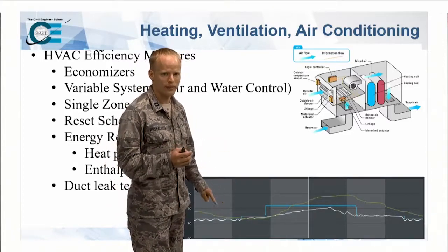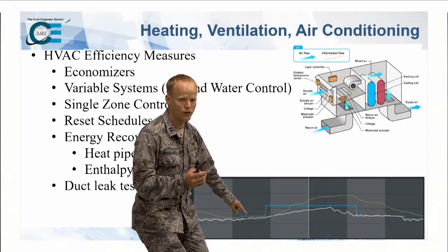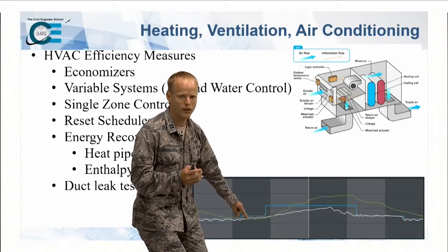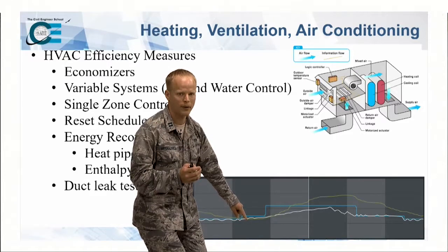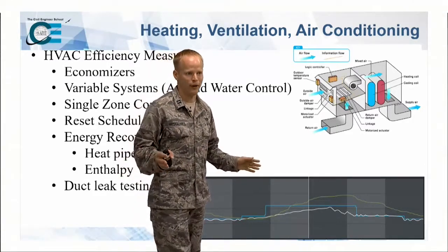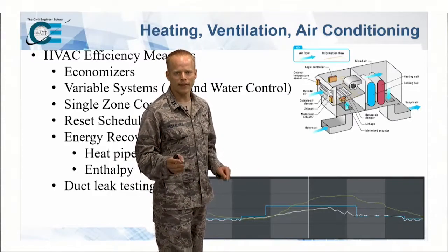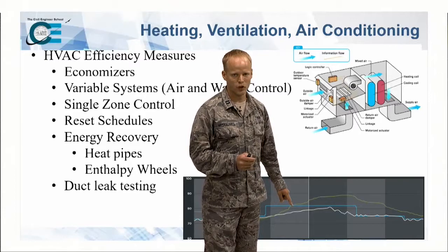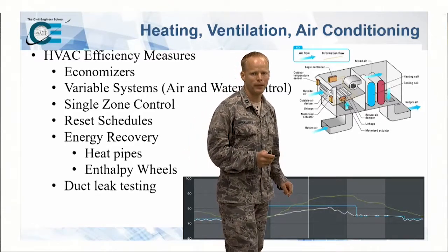Then in the morning, I don't need it cold, so it increases the temperature. And I allow my temperature to slowly rise up in the morning to that set point. I'm not using any cooling at that point. Then, during the day, when I'm not there, why bother cooling it? So I let it creep back up.